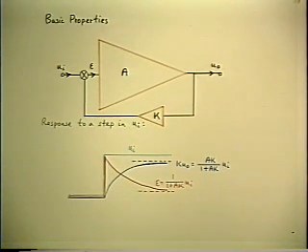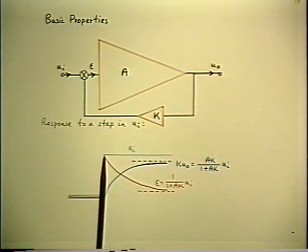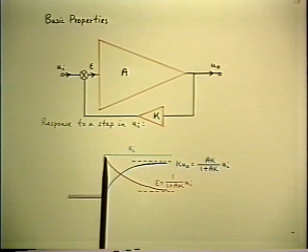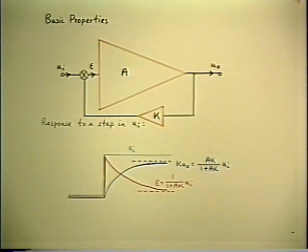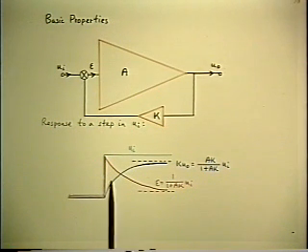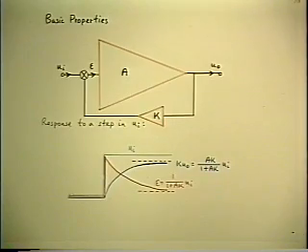When you look into that problem a little more carefully, you find that what really matters is the rise time of the input step, which is not going to be instantaneous anyway. What matters is the rise time relative to the slew rate, to make sure you don't go into an overload if that's a particular concern. But again, the way to tackle those problems is to break down the analysis into smaller pieces.